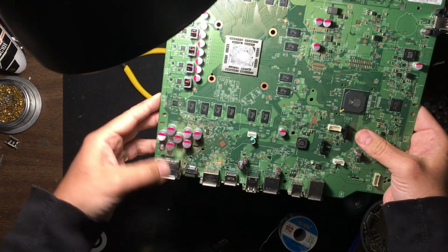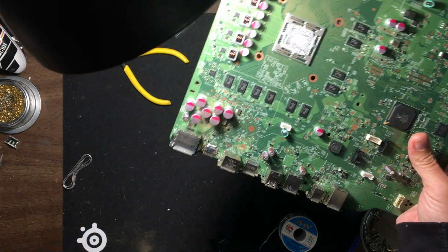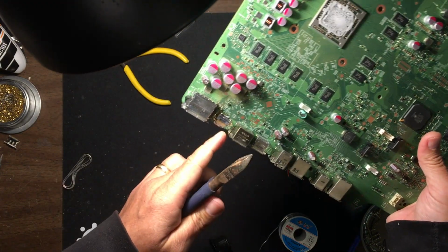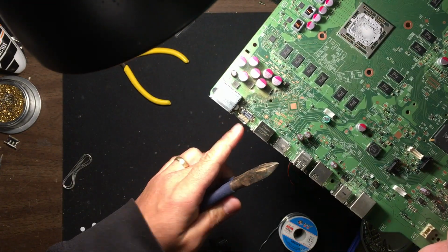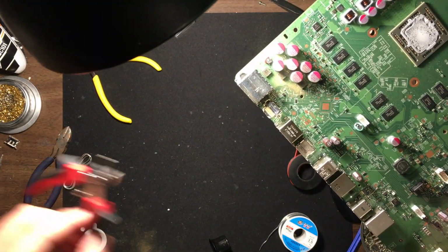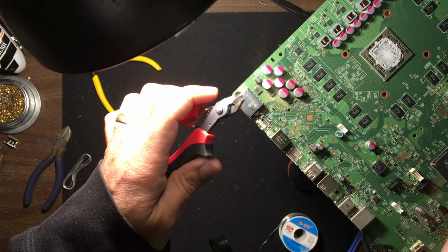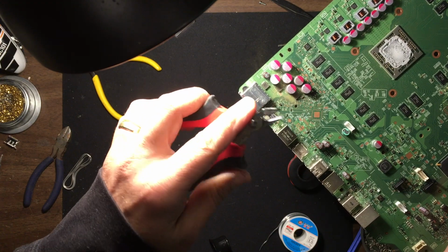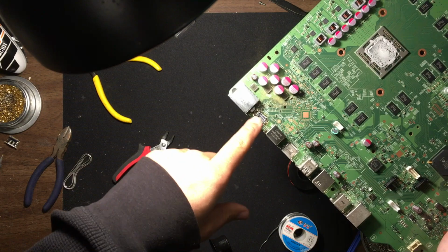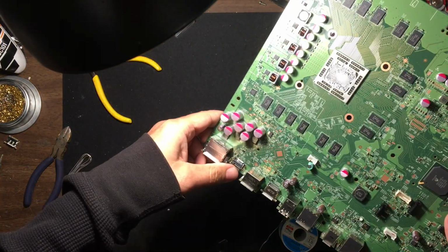Okay, so at this point I've got the pins completely cut and independent. I used a combination of these little clippers here to cut away the sheet metal. I bent it back, as you can see here and there. I'll show a close-up when I finally get this thing off. And I used my clip nippers here, any kind of tiny little metal cutting thing. These are usually for wire. They're not as good for this kind of sheet metal. You can see I've got to clean all the stuff off. But basically, at this point, the underpins are not holding this on anymore.